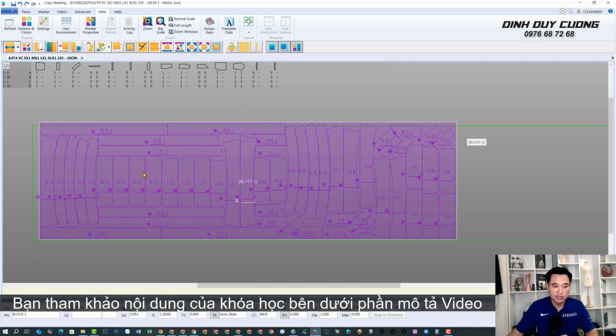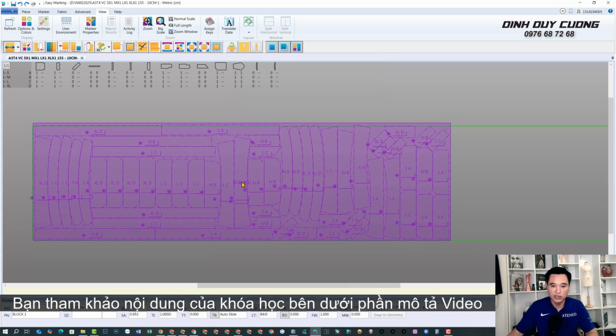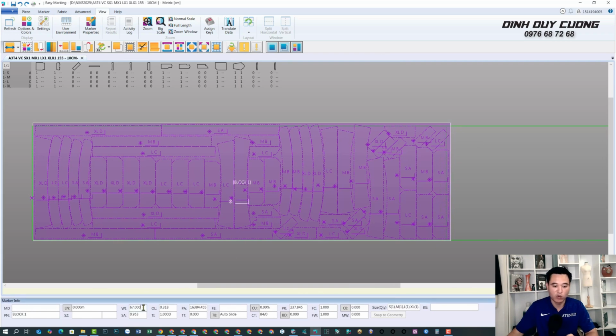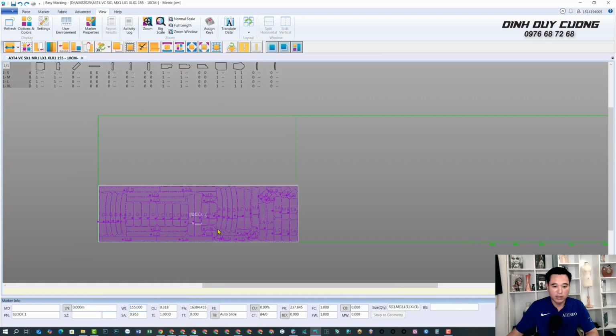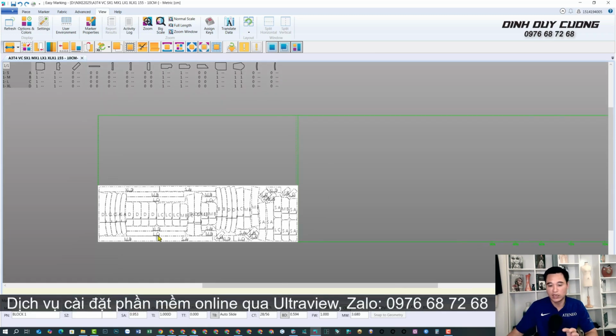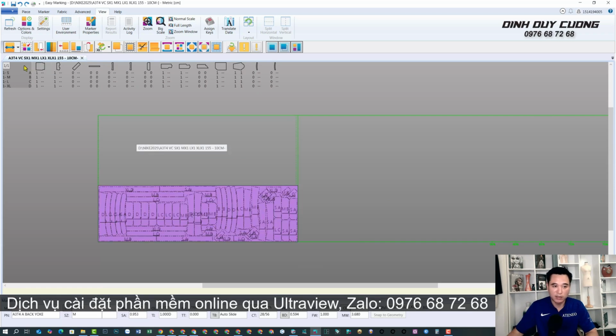Then this buffer area, the area around it, will be just as you selected, okay? So after you've selected this, now there's extra fabric size, so you'll need to adjust it back to the original fabric size. Enter. And at this point, you'll see that this is the part we will cut out to apply the adhesive backing. After that, I'll cut it into small pieces, which will ensure that our measurements are very precise. And after I've laid them out like this, now you can continue to lay out all the details that are up here. You'll right click and select all the details to move them down here, right?